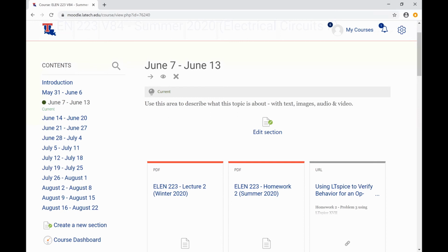Okay. So one thing, there are multiple ways to set up circuits for the transient analysis problems. The easiest way, in my opinion, is to set the circuit up and run a DC operating point analysis to get your conditions at t equals 0 minus. Then I would set up my initial conditions, and I think I talked about that a little bit in the first, let's see.